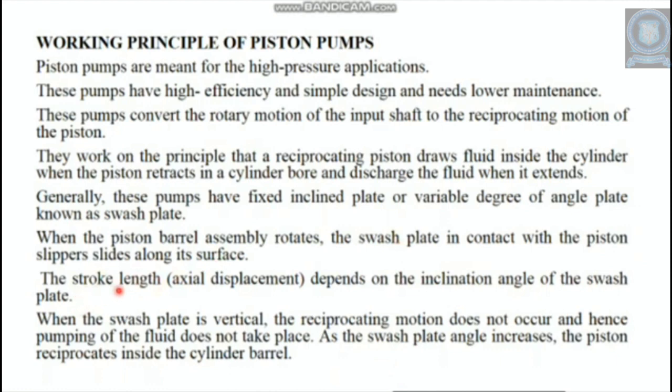The stroke length depends on the inclination angle of the swash plate. When the swash plate is vertical, the reciprocating motion does not occur and hence pumping of fluid does not take place. As the swash plate angle increases, the piston reciprocates inside the cylinder barrel.